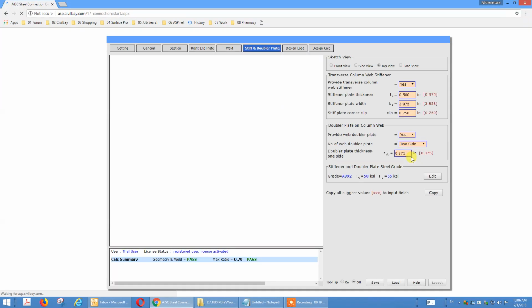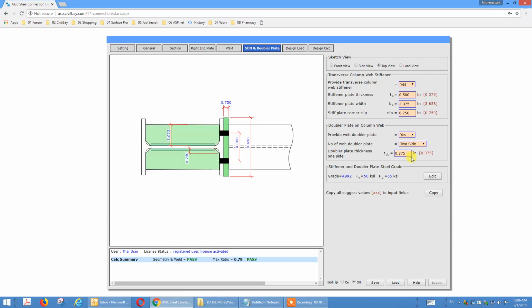The double plate man-hour labor cost is very high, normally much higher than the material itself. In AISC, increasing column size is called a clean column, without stiffener plate or double plate, but using a heavier member. So here the double plate is on both sides.